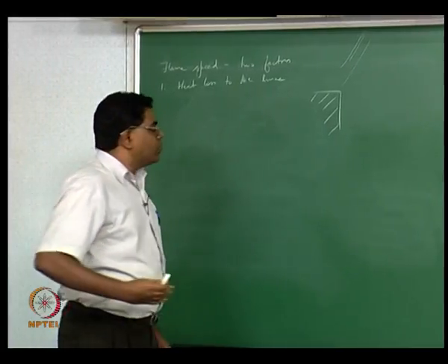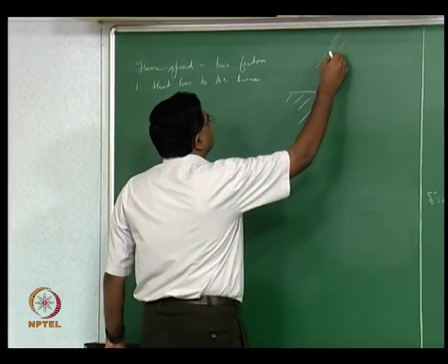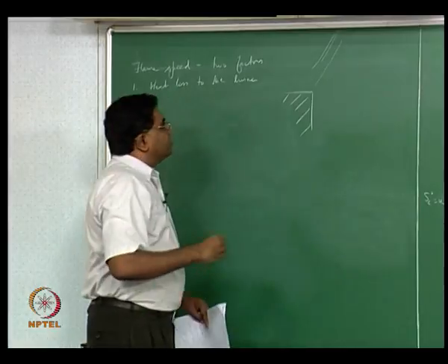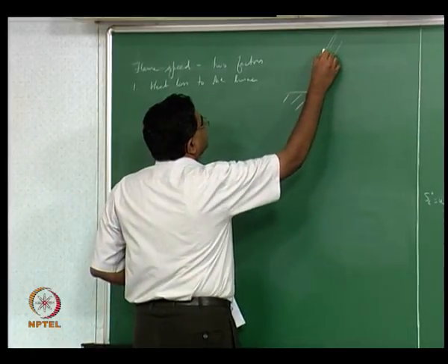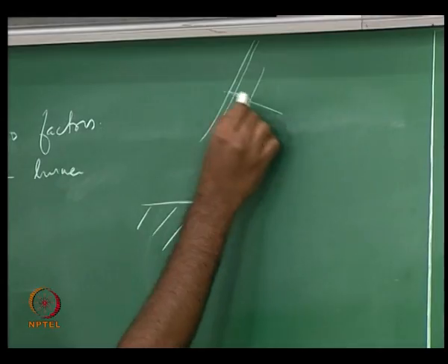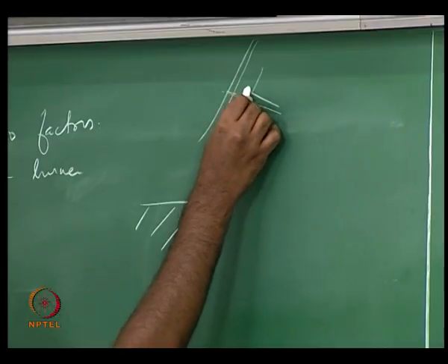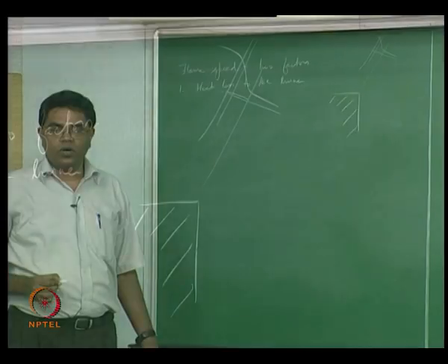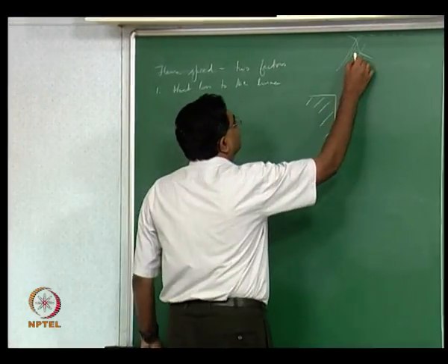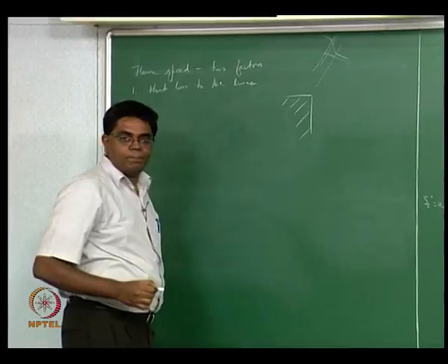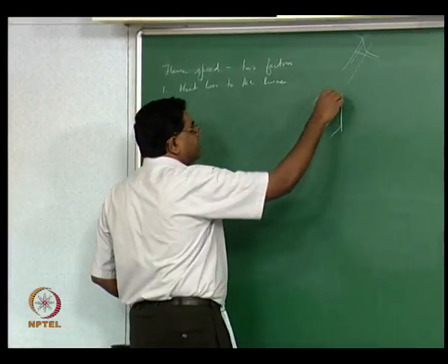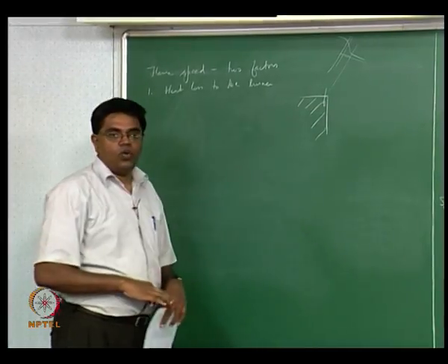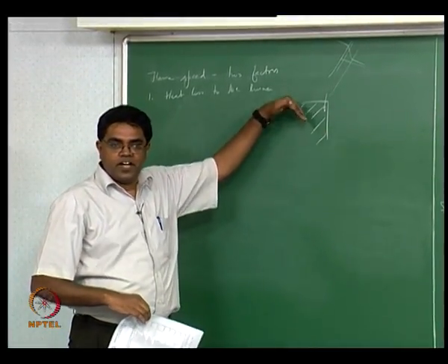But what happens as you progressively come closer to the rim is, keep in mind that this is the region where the temperature rises from the initial temperature to the flame temperature as we go along, and this is the region where most of the conduction is happening. But as you now come down to the burner rim, you now have a heat conduction that's going on inside the rim as well.